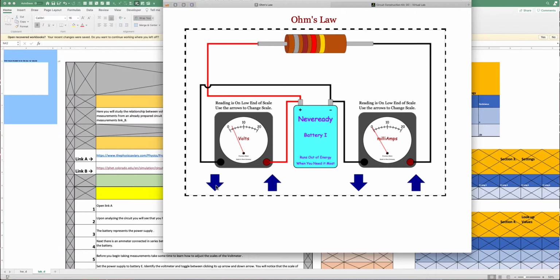So for example, for this voltage here, this scale is too big. So let's go to another scale. Here this is 2.5, that's okay, but I would recommend reading it on this scale here. Here it's going to be the same in both cases, but there'll be other cases where it's always best to read the scale on the one that has the most sig figs. So here this would be 2.5 volts.